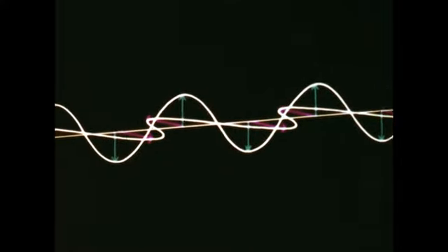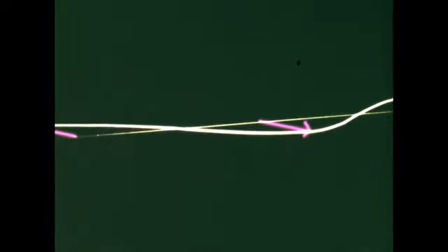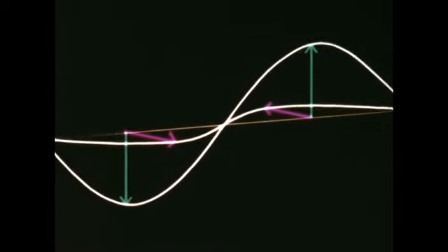The polarity of an antenna is determined by the plane of the E field. To obtain a maximum signal, both the transmitting and receiving antennas must be in the plane of the E field. The direction in which the E and the H wave pattern propagates is determined by a simple rule.